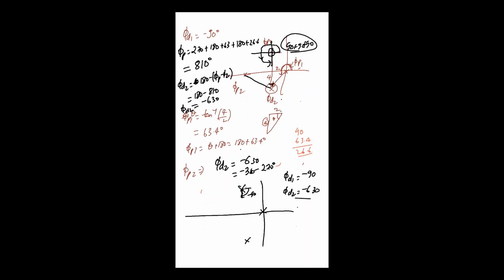So root locus branches will go downward. So this branch has to go upward to make it symmetrical, or mirror image, which is a property of root locus. This is our real axis. It has to be symmetrical about the real axis, right? If it is going downward, it has to go upward. Let us say that we want to calculate phi d2. We do not want to rely on the property. That is what I have tried to show you.